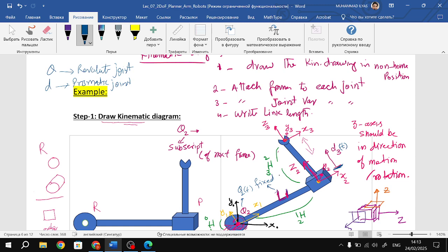You have to be careful, because when you derive the differential kinematics, you should first understand which values are fixed and which variables change with time, because you have to take derivatives with respect to time. The derivative of a fixed value will be 0, but functions of time are differentiable. In problems, it will not be D3, there will be some other variable. If it is fixed, it is a link length. If it is not fixed, it is a joint variable.